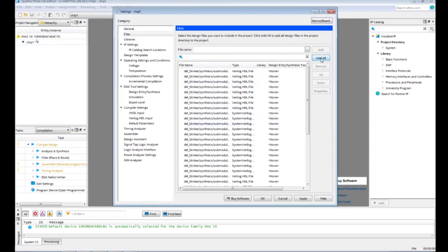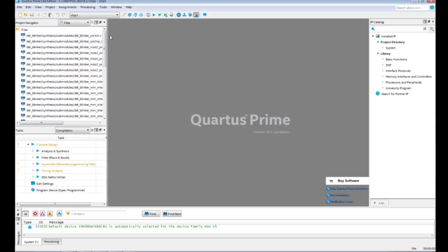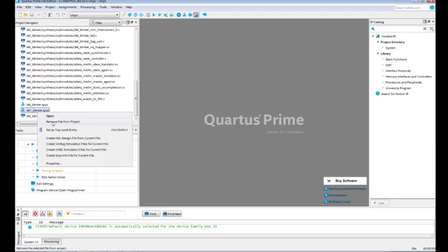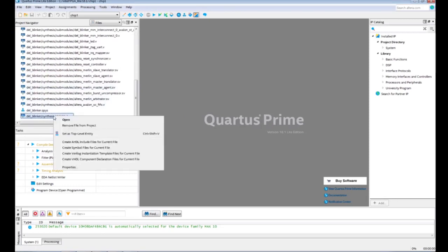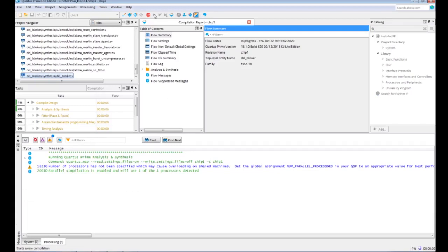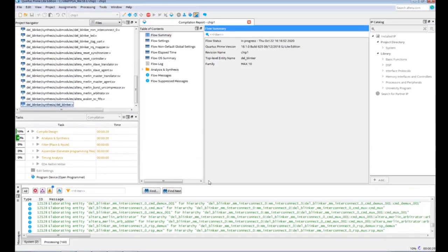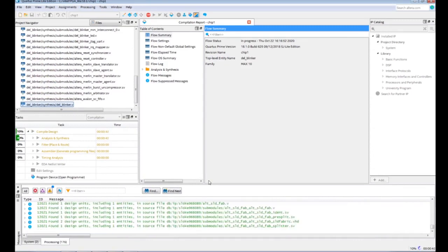After adding all the files which were generated by the program, and setting our circuit file as a top level entity, we will compile these files into the project, and then we will start assigning our pins to the switches and LEDs, which will take the input, and the LEDs which will display our output, and our clock, and then compile again and upload the program on the board.